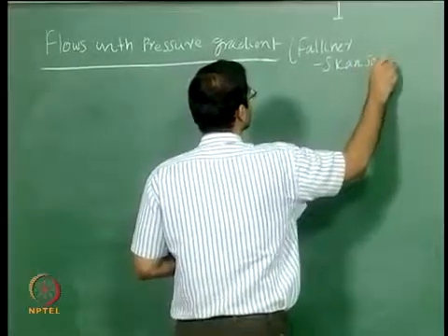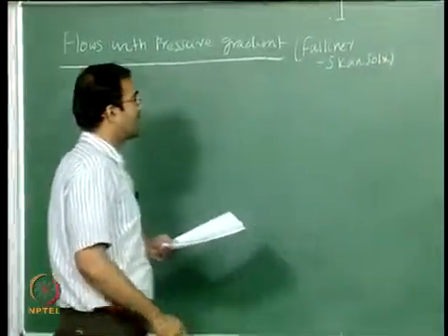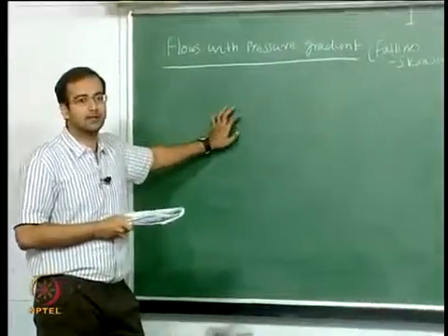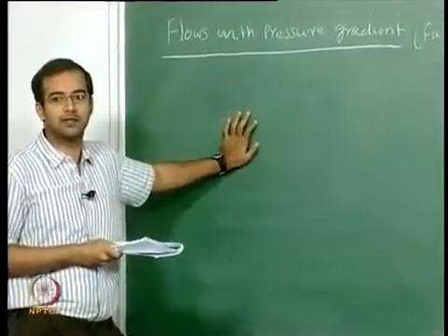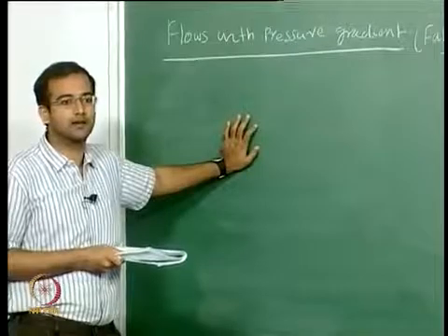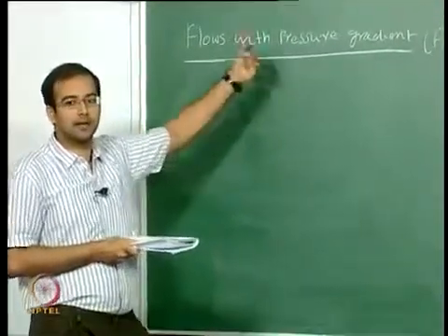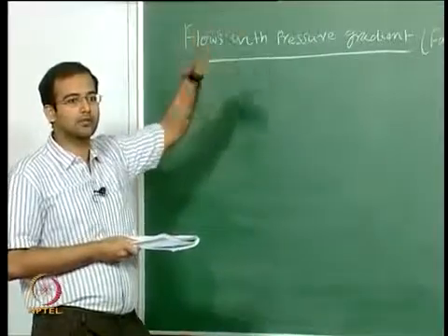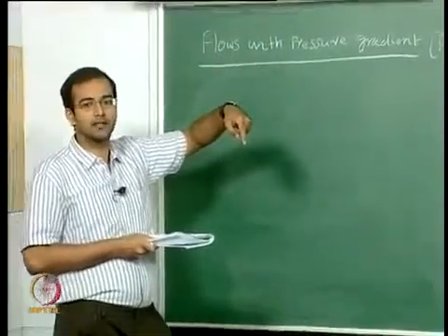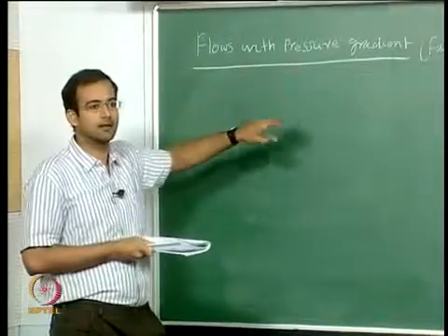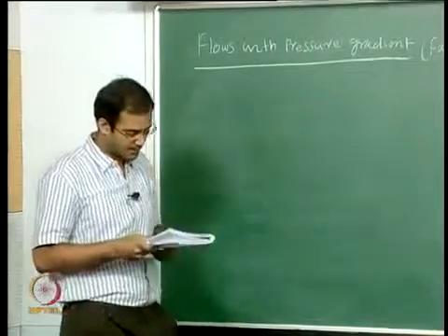The heat transfer part was added to the flow part because the heat transfer equation has nothing to do with the pressure gradient. The heat transfer already has been solved. So once you solve the flow, that f that comes out of the flow goes into the similarity solution for temperature. That is going to be much simpler. So the flow is the major complication here.